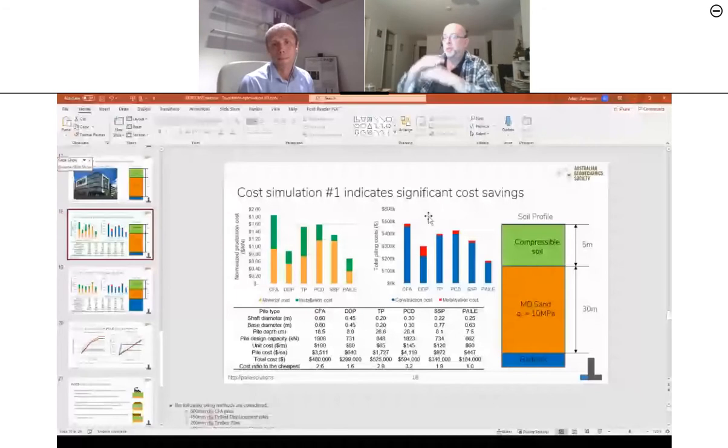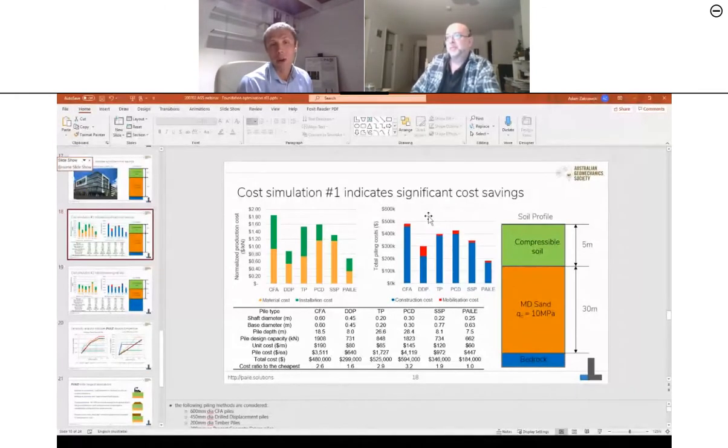When you spread the helix out, what's the preload that's applied to the soil at that stage? Well, it's basically the force that we need to apply to open the helices, and that is driven by either the resistance of the soil under the bottom helix or the resistance of the soil above the top helix, as you can imagine. So the top part draws resistance from uplift resistance of the external pipe with the helix.